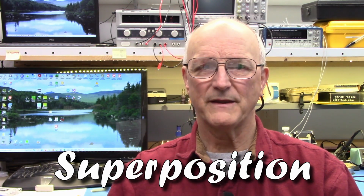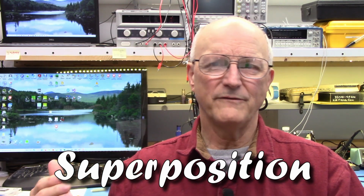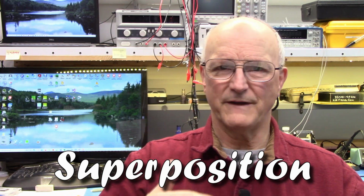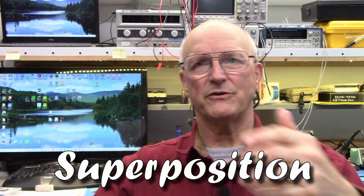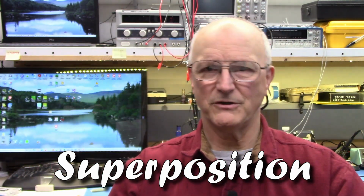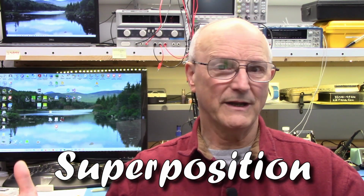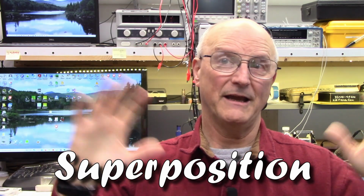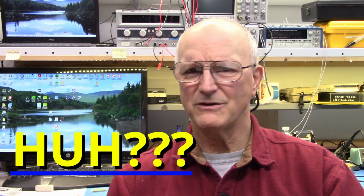Now, superposition is the art of turning off all but one voltage source and solving for circuit values. Then you move through the circuit one voltage source at a time, turning off all others except the one you're looking at, calculating circuit values, and then doing some accounting in the end. And in the end, you end up with the right values for all of the circuit values. Now, I'm sure that this sounds really confusing, so let's take a look at this at the whiteboard and maybe we can just unravel it.